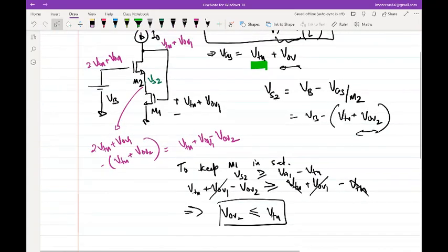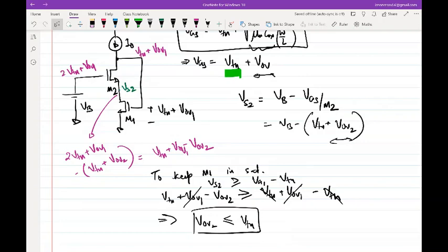Why are you not assuming a general VTH? No, you can do that also. There is nothing wrong in doing that. The reason I am not doing that is because circuit designers don't think like that. The way we think is, let's assume that everything is in saturation. Then we figure out the limit at which the transistors are in saturation. We start off from there. Then we look at margins, because the edge of saturation is not a very good way to bias: if something moves, things will go out.